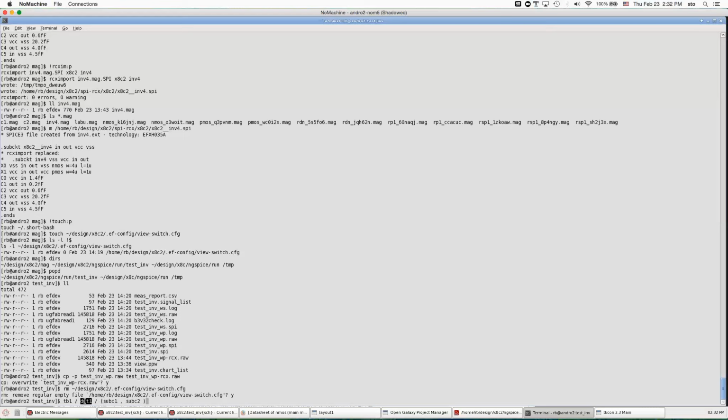And then when this is switched in to the schematic, in place of the schematic version, there's no question that the RCX version of that includes all the circuitry that came from what in layout were subcells, but in the netlist it's all locally flat. So all the layout stuff is added.